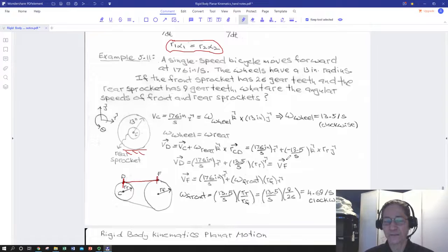There is no slipping. And as a last note to rolling, there are some books that will talk about rolling with sliding and some kind of combination. From the standpoint of what we're studying, the entire concept of rolling hinges on that point of instantaneous zero velocity at the contact. So if there's sliding, everything we've just done in this rolling section goes out the window because our basis assumption is now not there.